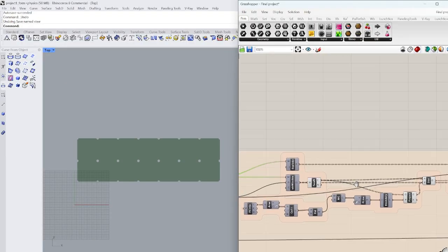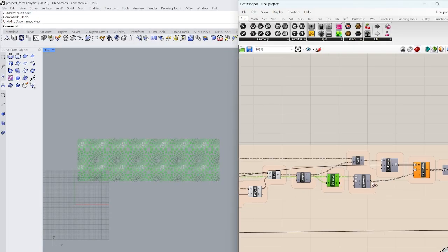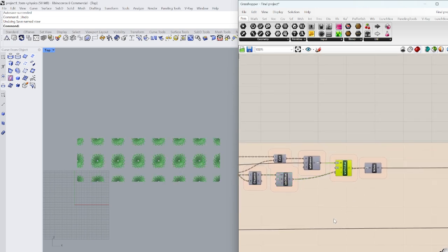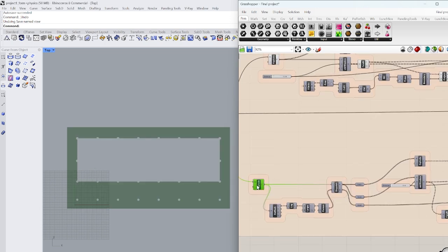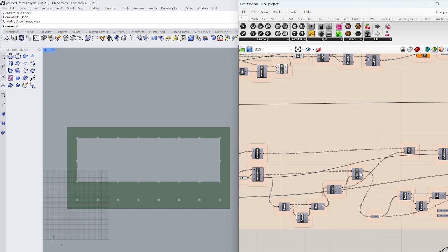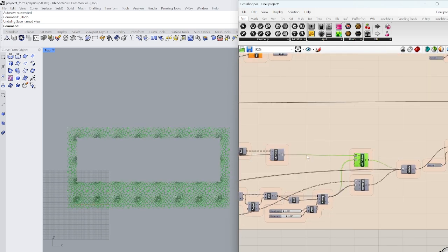First, I exploded the mesh, then got the normal for each face, and then used Dispatch to get rid of the extra pattern, and then used Weaverbird Thickness to have the thickness. For the exterior roof and the example below, I did the same thing. Used Dispatch and then Weaverbird Thickness also to have the thickness.